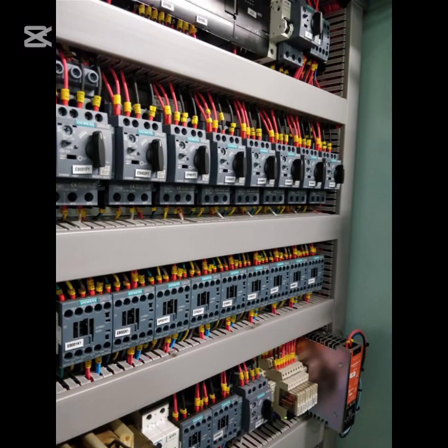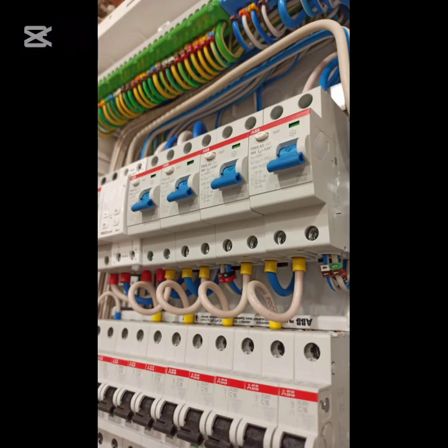Stranded wires offer greater flexibility for navigating around obstacles, compared to solid wires. 4. Flexibility. Stranded wires are much more bendable, although over time, the flexible strands may break at terminations. Solid wires maintain their shape better, but can break if bent excessively.